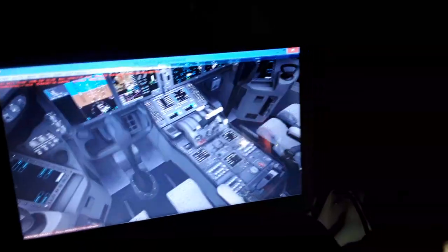So we have also the rudder pedals for vertical rudder yawing turns in the air. Also for nose wheel steering on the ground, it's interconnected with the tiller until some airspeed, like 70 knots. Then we have the rudder function when the rudder is aerodynamically effective on the runway for takeoff. So we have also the toe brakes and the rudder pedals. So the elevator in the control column and the column pulling up and pulling down like this.